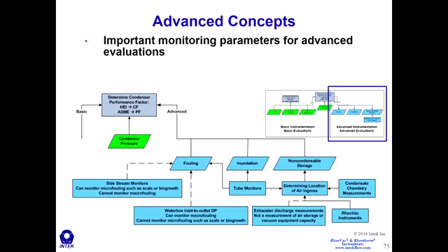And this is a method that ASME PTC 12.2 recommends for quantifying fouling, and we have made some improvements on some of that instrumentation to monitor fouling that I'll talk about in the next couple slides. Those instruments can also measure inundation. This is a factor of the design. This is water that creates that resistive layer on the outside of the tube and impedes heat transfer. So you can do some inundation analysis with that.